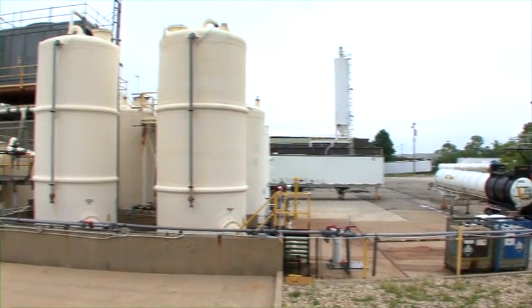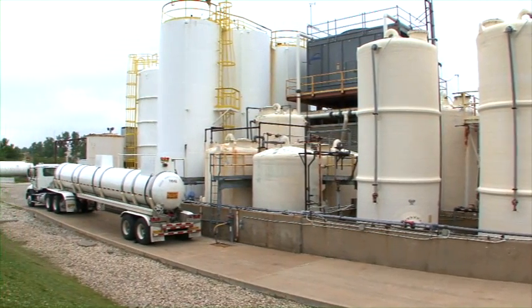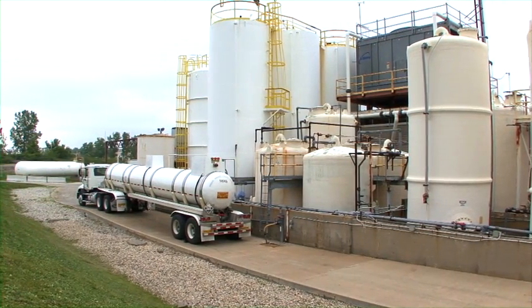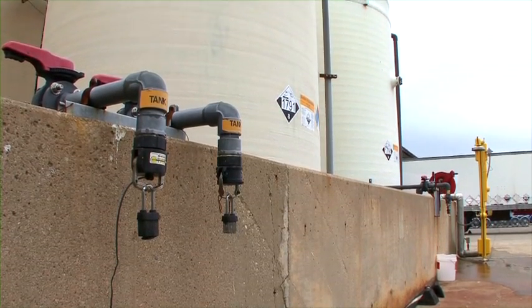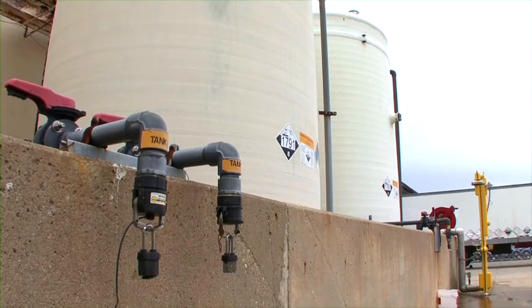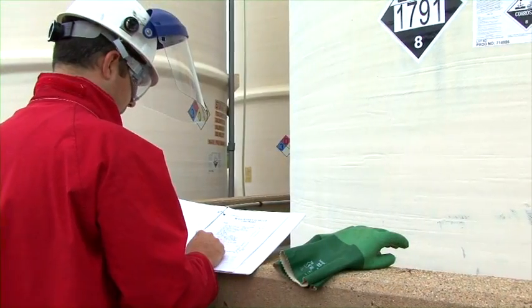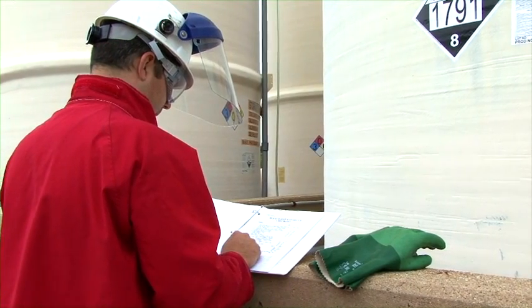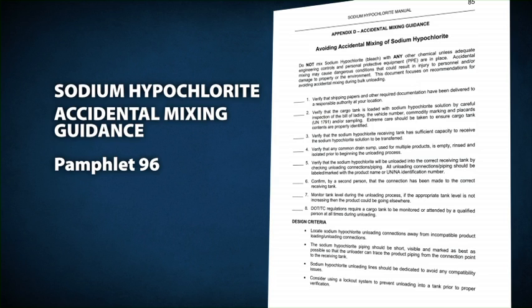Before unloading any sodium hypochlorite container, employees should be knowledgeable of the proper unloading procedures established by their company and the supplier. A best practice is to separate unloading lines for different products. All unloading lines should be clearly labeled. A facility should establish a checklist that is readily available for safe unloading, detailing the proper procedural steps. Use extreme caution when common lines are present for multiple products.